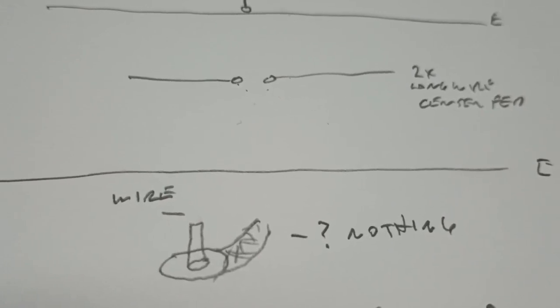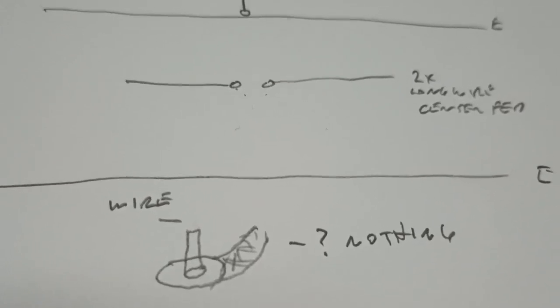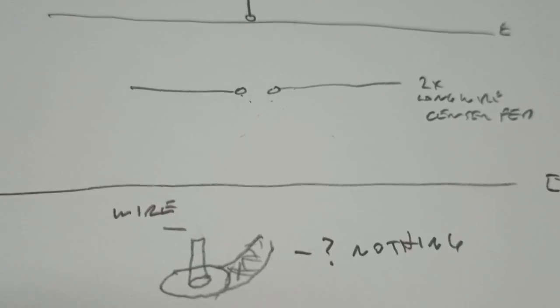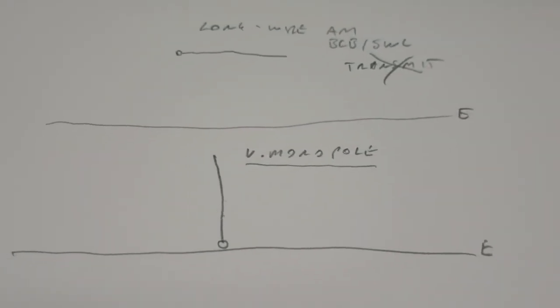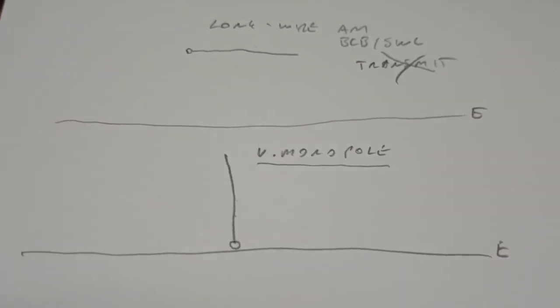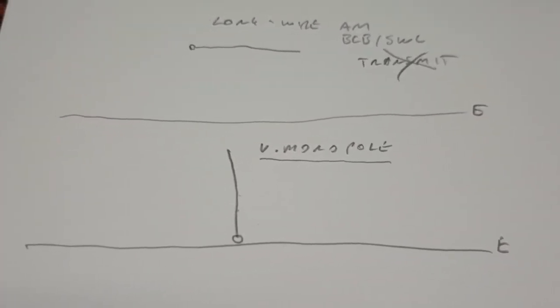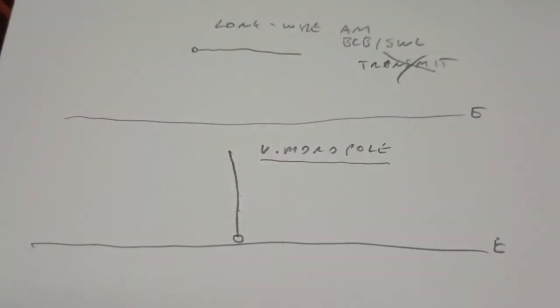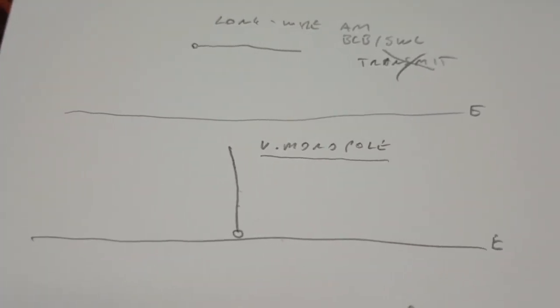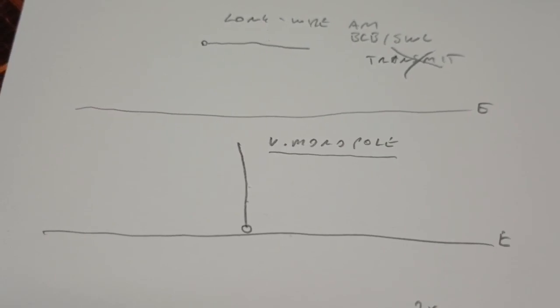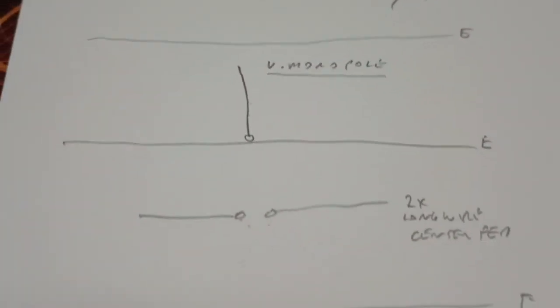But see, it's obvious that transmission line has two places to connect with on a dipole, but not with the end feds, and those are both end fed. It's impossible to feed both ends, because if we try to do that, we make a loop. If we fold the end back over, we make a folded inductor. That's not an antenna.